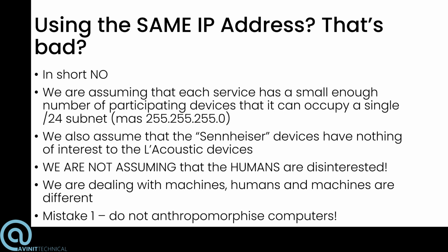What we're doing, like I said, is making an assumption that each service has a small enough number of participating devices that we can occupy a single /24 subnet. We also assume that the Sennheiser devices have nothing of interest to L-acoustics devices. We're not assuming that the humans are disinterested. Obviously, a systems tech may want to control the amplifiers and then may have some responsibility for managing radio mics or mixing consoles, of course.